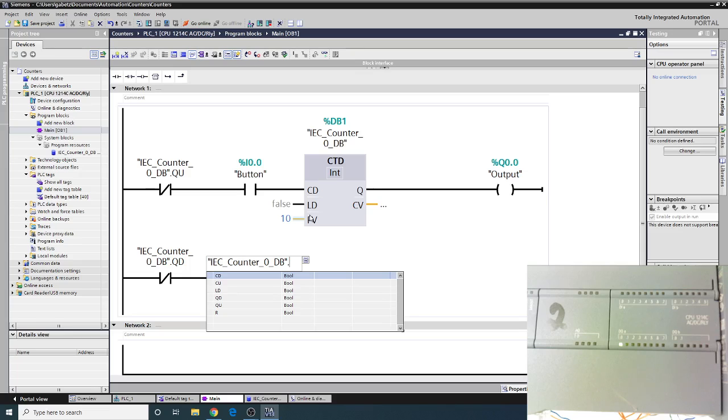Maybe a better option, instead of bottles, you'd say pallets. Because you could say, okay, we've got 300 bottles on a pallet. We could just say one pallet is 300, and then somewhere you could have a little math operation that says bottles equals pallets times 300, and then on your HMI you would just say number of bottles, or completely packed or something, you'd go 300.